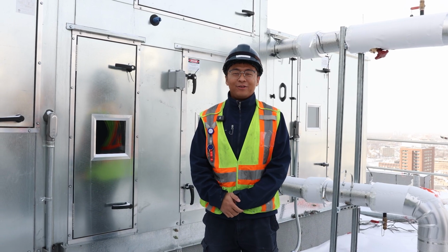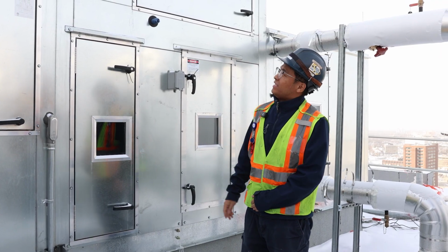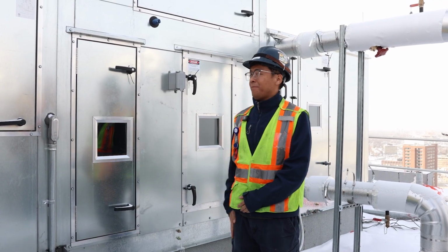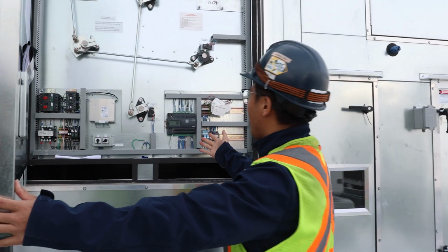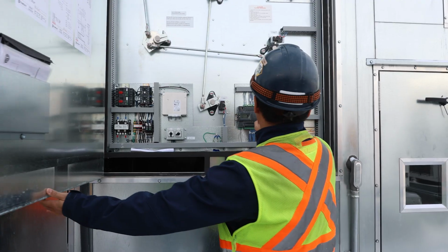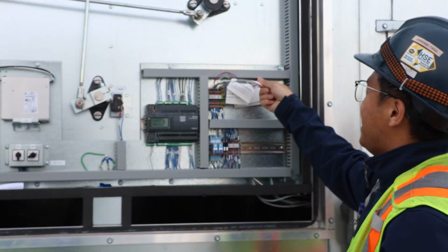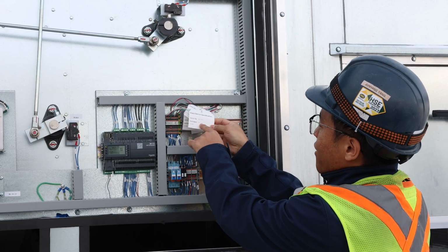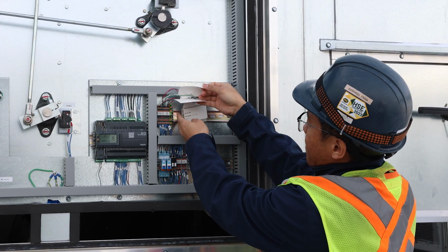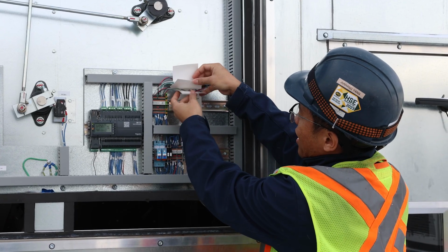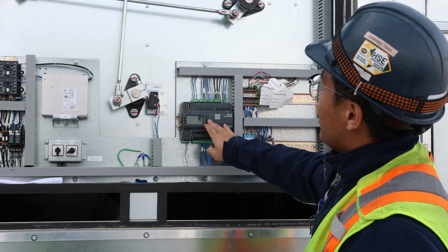Hello, everyone. Welcome to the penthouse roof. Now we are looking at the ERV unit. This ERV does the fresh air to the building, and it has the internal panel. This is the internal controller, and this will be the BMS signal. So BMS does the ERV command, heat recovery mode or recirculation mode enable. We also pick up the damper alarm, low limit. This is the BMS tag and the ERV internal panel.